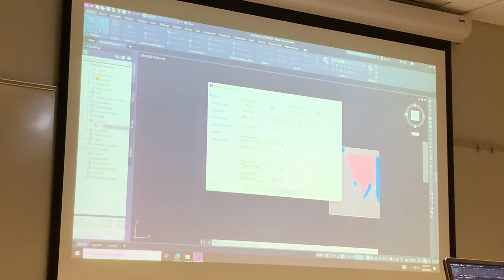I did not change anything. I just checked to make sure that the proper alignment and the proper sample line group were selected. And then you can give it a name if you want to, but if you specify a name here, it's going to make the name of every single one of the cross sections the same. If we leave it like this, you'll see section view station. If we left the station there, then we could put something afterward. But aside from that, next, on the section placement, we'll choose draft.